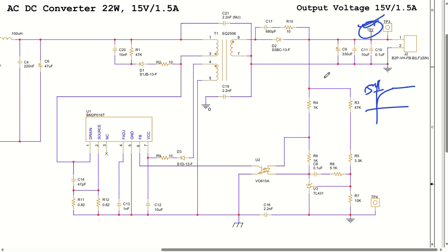What we will be doing is designing a voltage divider circuit using this resistor, which is only one resistor, R3 and R5 together being a single resistor, and R7. These two resistors put together give this voltage, let us say Vx, which can be my V reference.